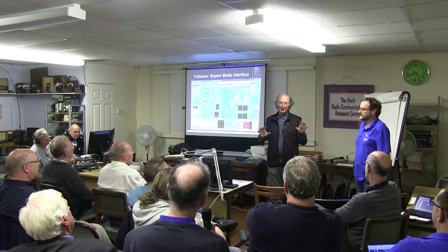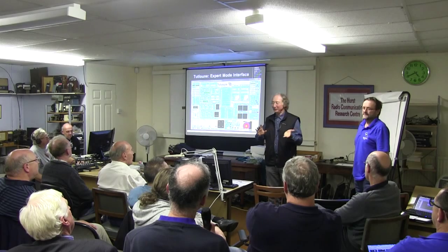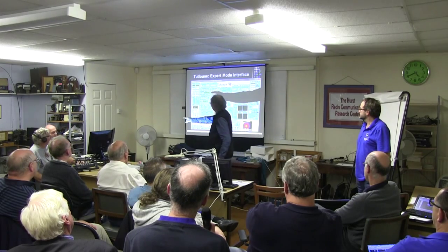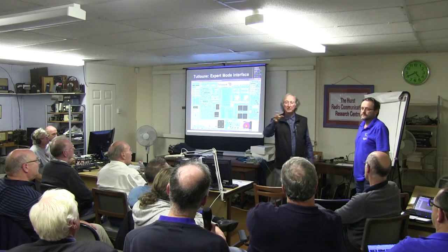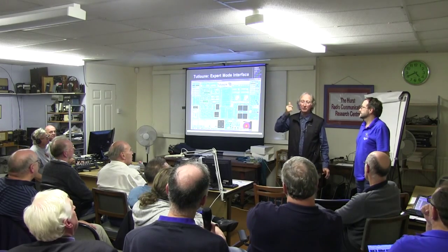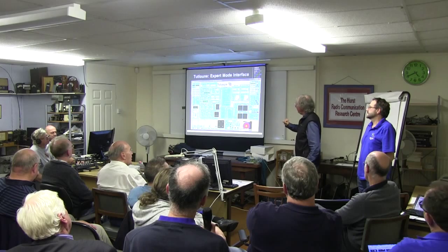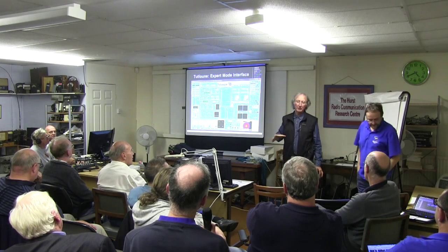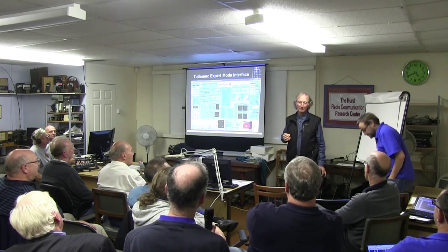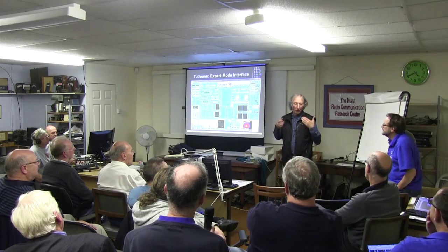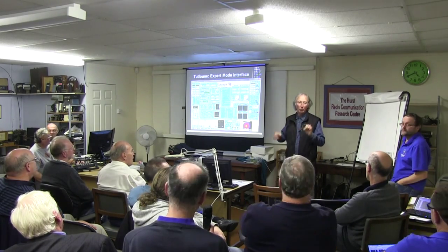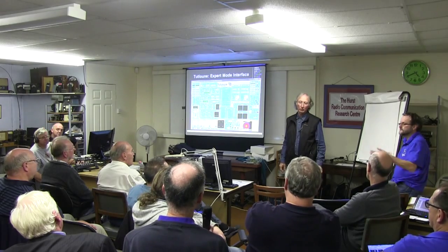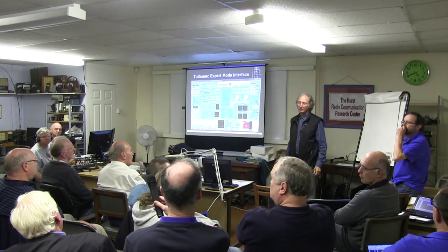Low symbol rate mode is from about 120, depends on the quartz, to 6,000 kilosymbols. So, for us, for ham radio, I think it's better to always stay in low symbol rate mode. Okay, thank you. Anybody else?